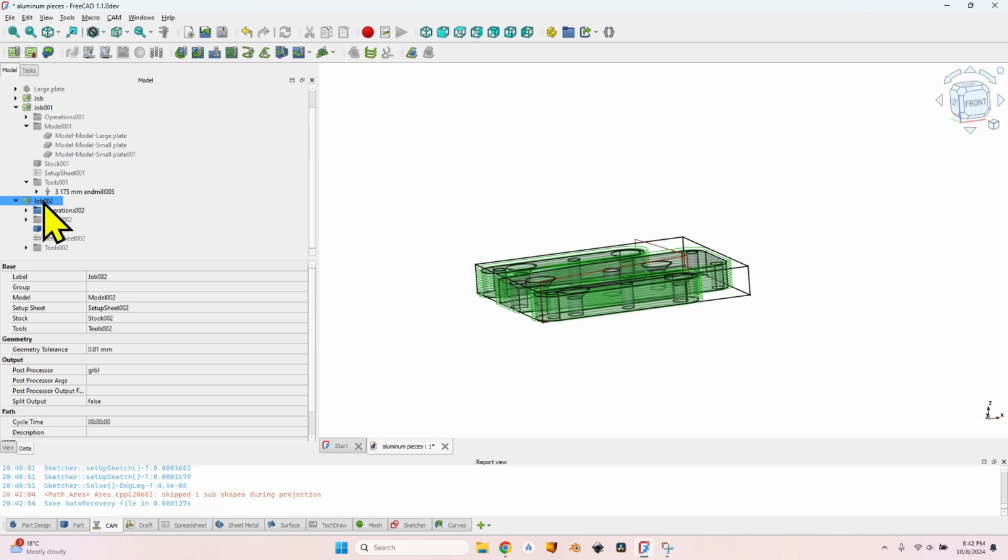You can look at certain other operations, remember what worked, what didn't work. For me in this situation, I've taken a look at an older operation, and each time I mill again some material that I have already milled, I try to push things a little bit farther, push the speed a little bit higher, and this way I can make sure I won't damage too many tool bits, but I try to improve things to make things work faster.